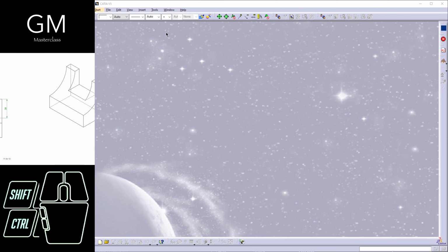is the information within the views, within the engineering draw. So right here I have these three views, and one step that I should take for me to start creating this 3D model is to select the view that contains the most information possible. As you can see right here, I have 2 dimensions. Right here I have one dimension, and right here I have 1, 2, 3, and 4 dimensions. So the one that I'm going to start using for me to create this 3D model is this view, right?